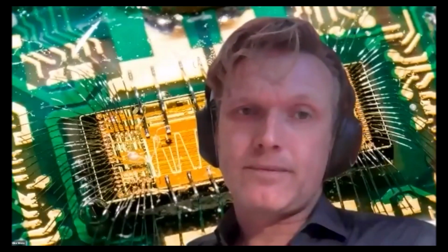Yes. That's the reason a high threshold cascode is quite forgiving. Whether you have 8 volt, 10 volt, 12 volt, 14 volt momentarily, with a 20 volt gate rating, it does help. That's why the E-mode design is quite challenging, but on the cascode design, the bootstrap is quite forgiving, and you can work. It's not really challenging.